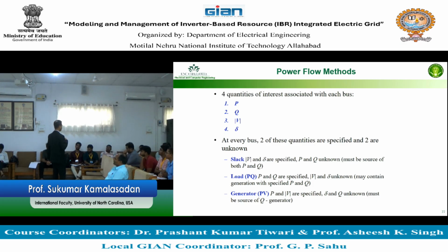So what is our thinking? I'm thinking that active power and the voltage I know. Why? Because I control them. So if I know active power and voltage, I can calculate the reactive power and the angle for the generator. So you may ask, all the buses are generator and load. Is there a bus without generator and without load? Yes, there is a bus without generator and without load.